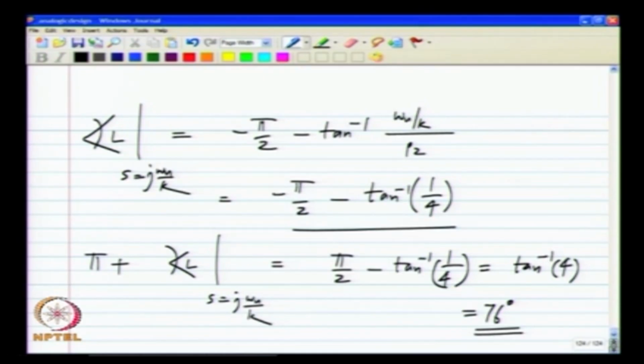Okay. So, that is the phase margin of a critically damped second order system, and we will apply that phase margin to all higher order systems, and it turns out that they will be well behaved. We will see some details of this in the next class, but that is how the Nyquist criterion is very useful. It helps us avoid calculating time domain response explicitly or the roots of the polynomials explicitly, while saying something about stability and good behavior of amplifiers. Thank you and see you in the next class.